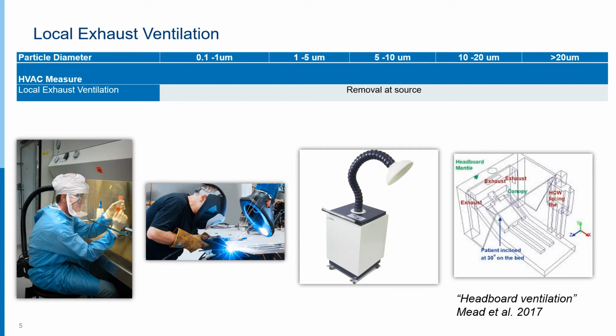So you can use local exhaust ventilation for gases, vapors, fibers, mists, fumes, dust. And we usually send them to some sort of cleaner to remove those contaminants at that point, or just exhaust them and get rid of them. There's all kinds of different configurations for local exhaust. You have snorkels and hoods and downdraft hoods and side draft hoods and canopy hoods and booths and enclosures. The list goes on and on.